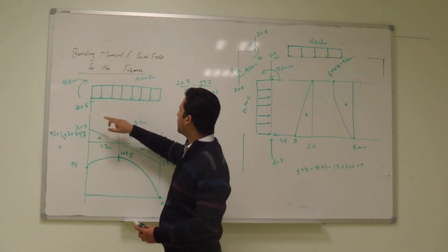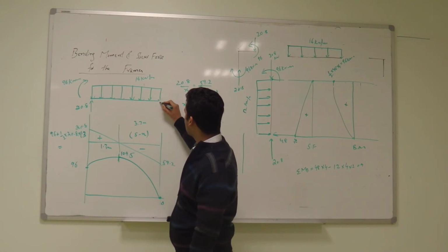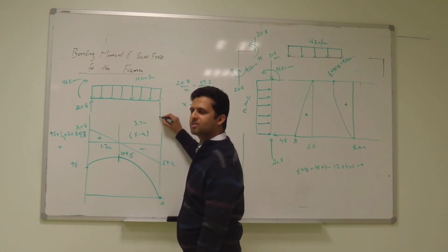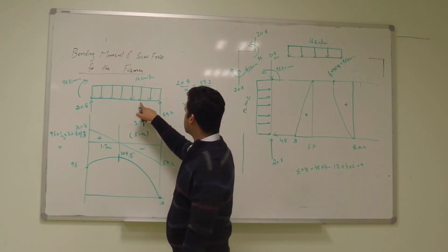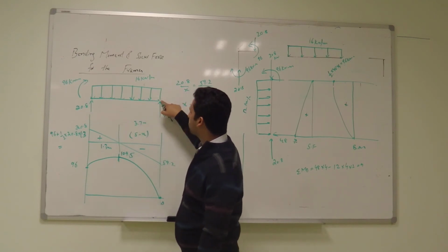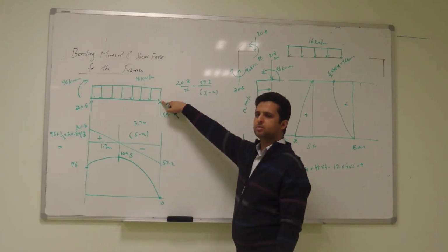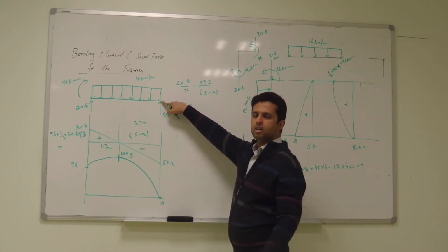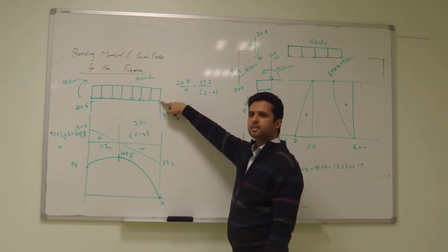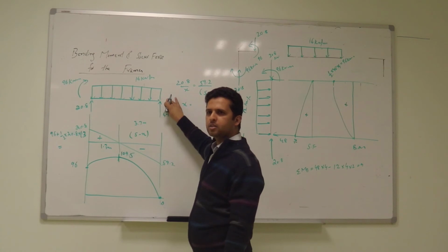So the vertical force 20.8. Do we need any vertical force here? Yes, upwards. It should be up, 59.2. And calculate the moment at this point. At this point, it should be 0. 20.8 into 5.6 plus 16 into 5 into 2, 96, minus 16 into 5 into 2.5. It should become 0. Yes, so zero. There is no moment, there is no need to balance any moment here.